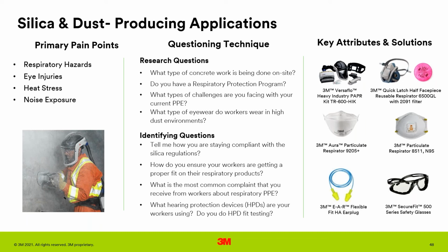Another one I'm going to point out here is our 9205, our N95. It's a great disposable respirator option for many construction clients, and they tend to lean that way. They're inexpensive and disposable, to be able to complete the task, but fit testing is required, and the worker does need to be clean shaven. So this respirator in particular is great.